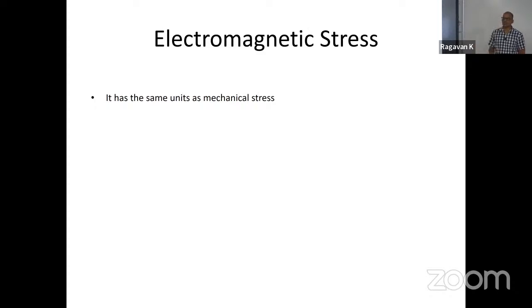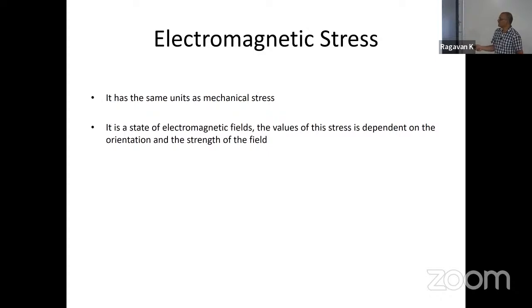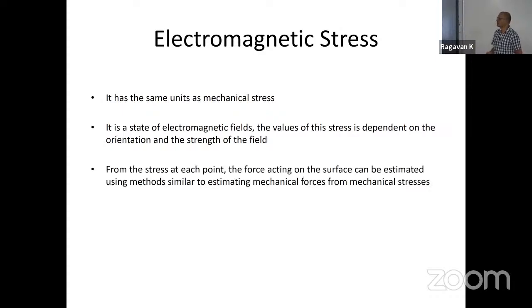We are trying to understand what electromagnetic stress is and how you compute forces from it. Professor Mahesh has introduced it for machines, so we will apply this to that simple example that I showed. It is a state of electromagnetic fields, that is what Maxwell has defined. The value of stress depends on the orientation and the strength of the field.